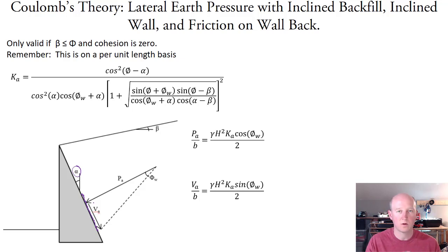One of the things that we're going to look at is, is this wall going to want to tip over? And if it does want to tip over, if there's something pushing down on the backside of it, that will stabilize it. And so this is another opportunity to be a little bit more aggressive with design. So it is a much more complicated equation. It is very conducive to programming into Excel so that once you get it set, then you don't have to worry about making an algebra mistake later.